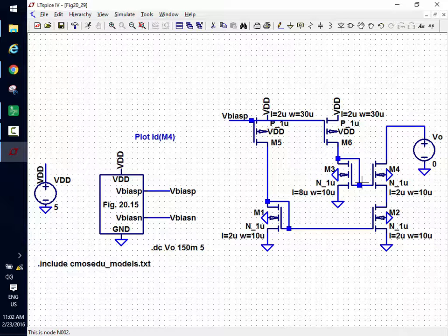So if I have a pipe and I reduce the diameter of the pipe, what happens to the pressure drop along the pipe? Say you have a garage and you want to run yourself some air tools. So you get some PVC pipe. I could get 1/2-inch PVC pipe to run the compressed air, or I could get 1 inch. Which is going to be more effective and drop less pressure from your compressor to your air tools? The bigger one's going to drop less pressure, right?